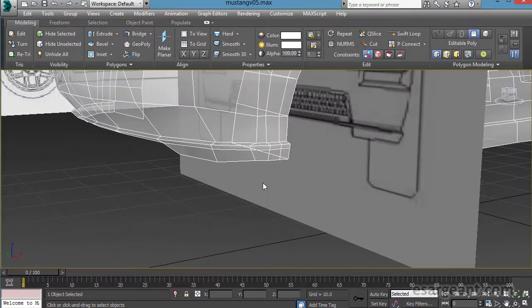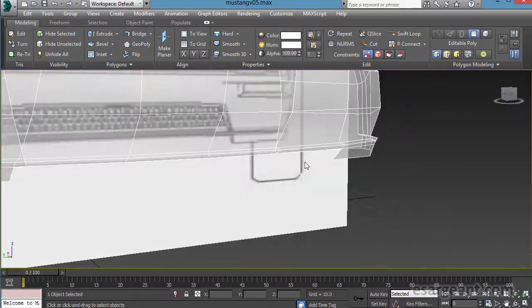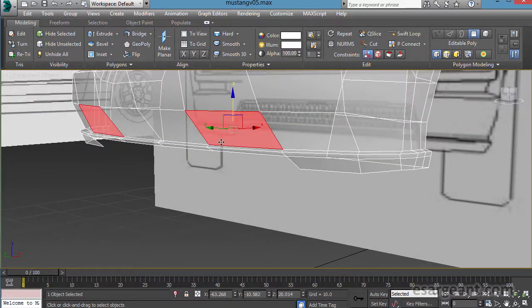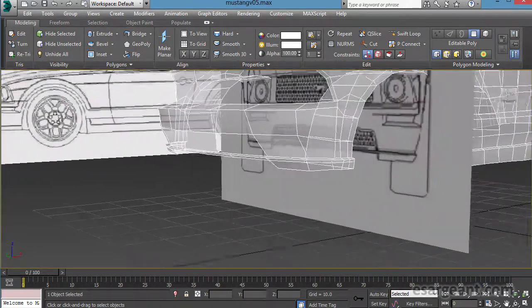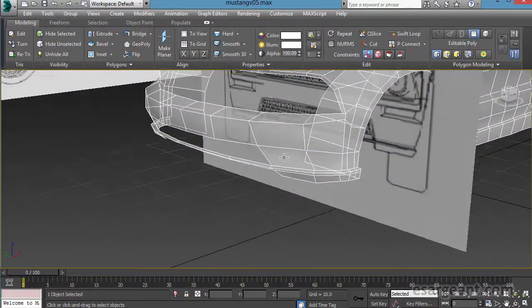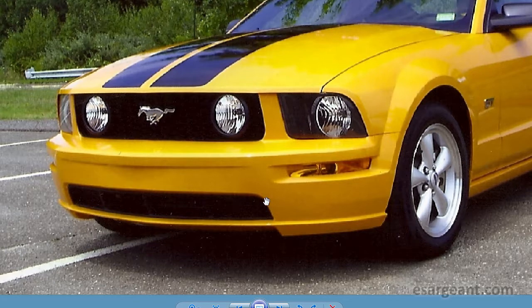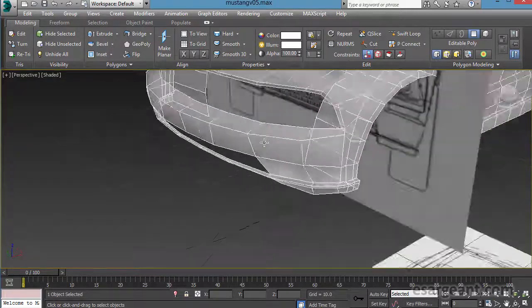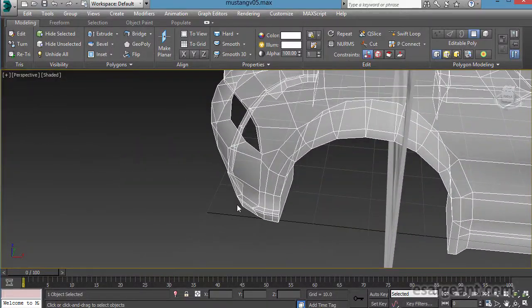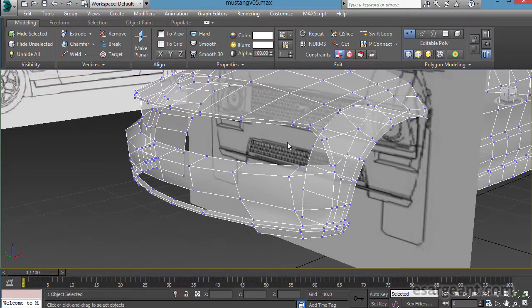And from the front, we can essentially do the same thing with these. Just delete those out. And then we've sort of roughed out that front shell with these cutouts here. We can build those in with separate geometry later. So that's a start on that front bumper. I'm going to start to refine these now and just tweak these points and realign everything with my blueprints, and then we'll catch up again. So this is where we are now after having done some tweaking.